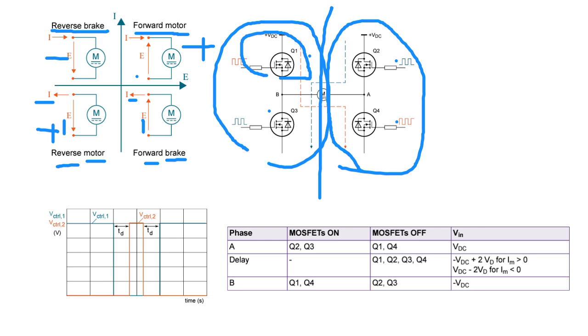You can use a relay in on position. Okay, in on position the motor works at the rated speed. If you want to regulate speed, you will apply a MOSFET, one MOSFET. If you want to regulate direction, you must apply two MOSFETs. If you want to regulate direction and the motor and regenerative braking operation, you must use four MOSFETs. This means H-bridge operation.